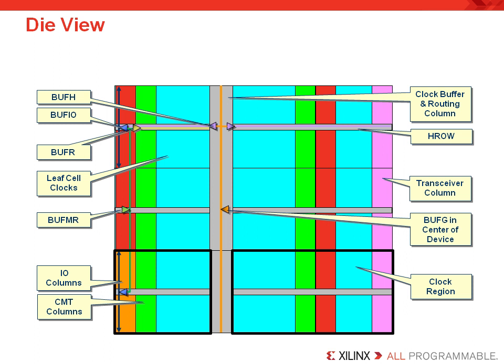Now, like Virtex-6, the clock regions are organized into rectangles that are divided by the gray column near the middle of the FPGA. This central gray column represents the global buffers and provides access to the global routing resources. In this example, the black lines, which are located at the bottom of the diagram, help you understand how a clock region is assigned. Each has a central gray line that splits the region horizontally.